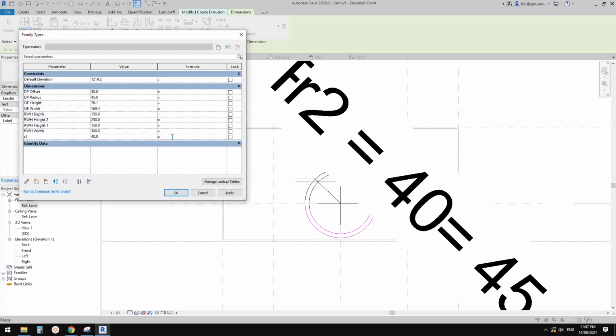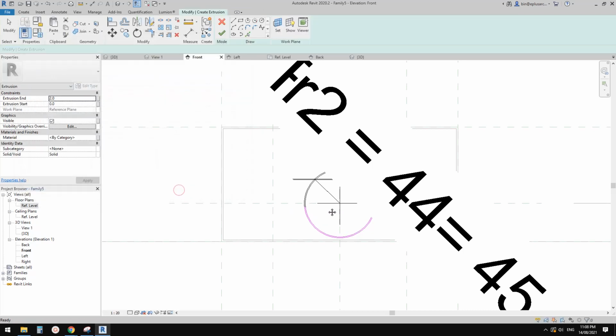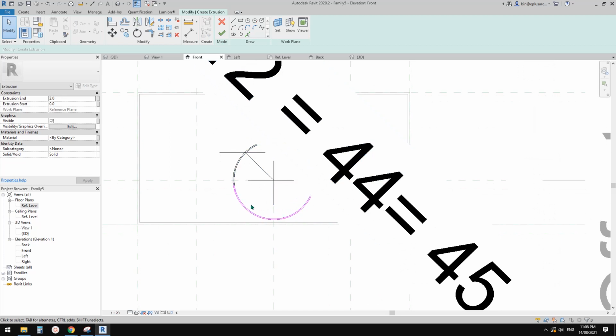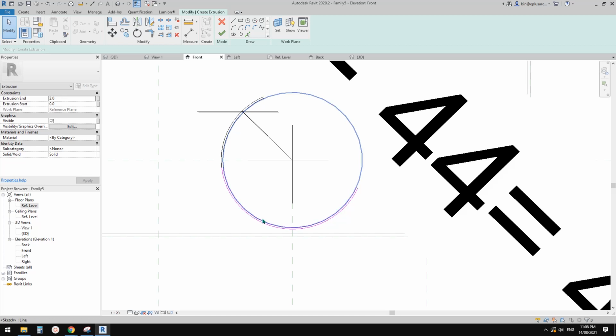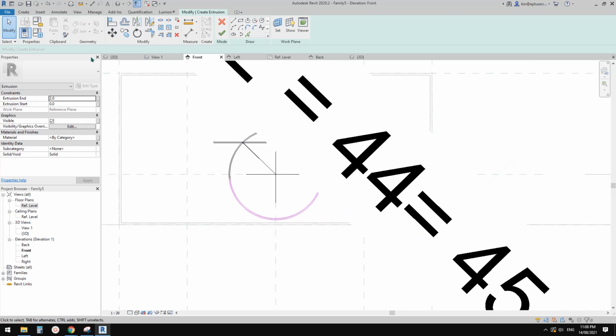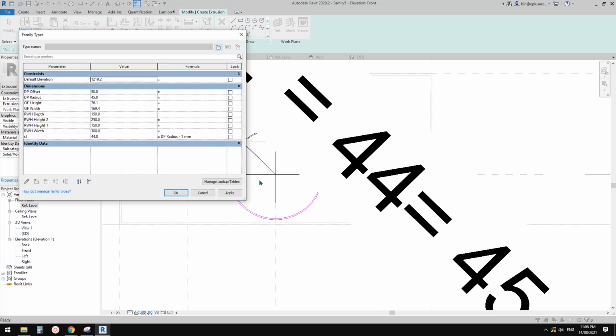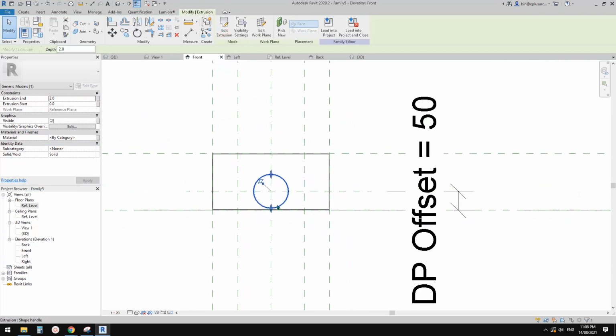And then for R2, you can use the downpipe radius, so minus whatever the thickness of the downpipe will be. So for example, I'll just minus 1, and then it will have this thickness. Oh, sorry, if I minus 1, that will be minus 0.5. So if you want the thickness of the downpipe to be 1, I think you need to minus... oh, if it's radius, that's fine. So it's correct, 1. And then finish it, so it will be a pipe.